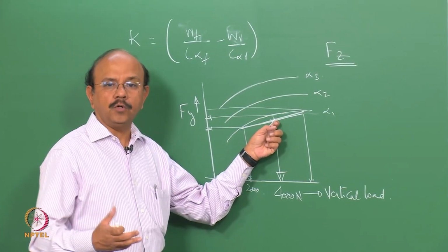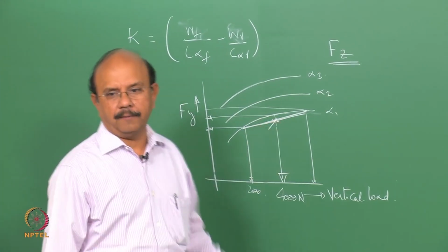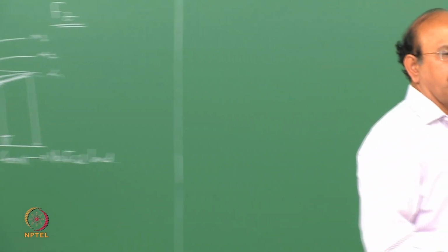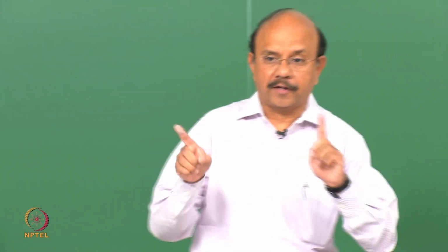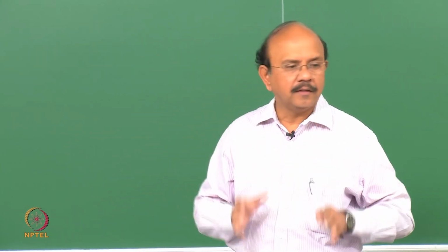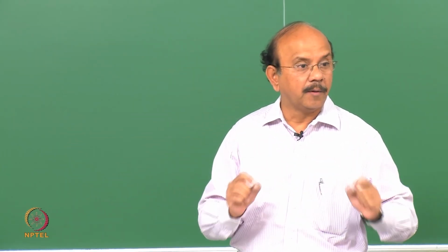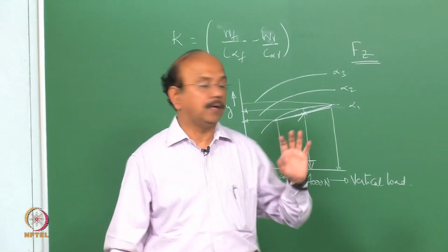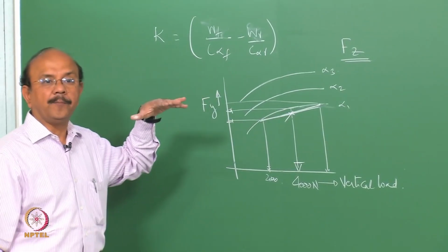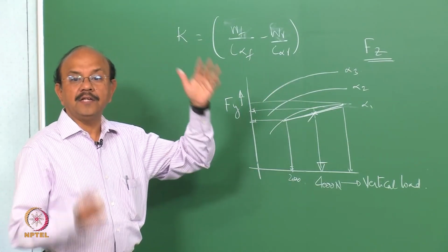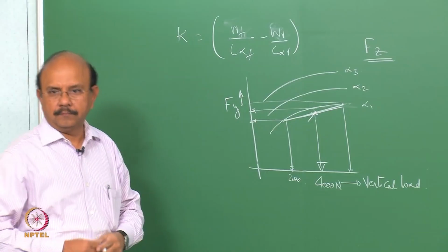So there has to be a larger alpha. There is going to be a larger alpha. Please note this is left and right. This is a tire, which is left and right. So front there is a left and right, rear there is a left and right. And remember that in our model we have C alpha F and C alpha r to depict the stiffness of the front and the rear together in toto.